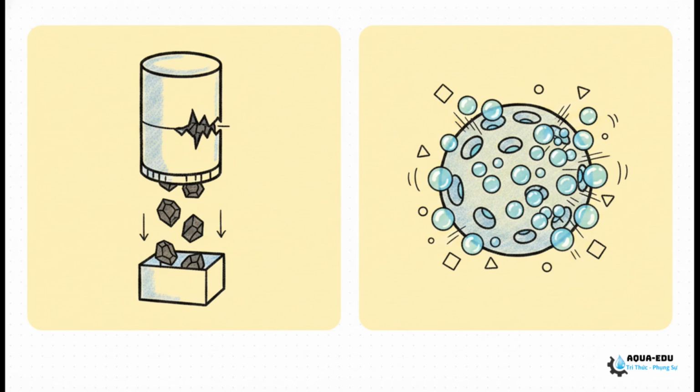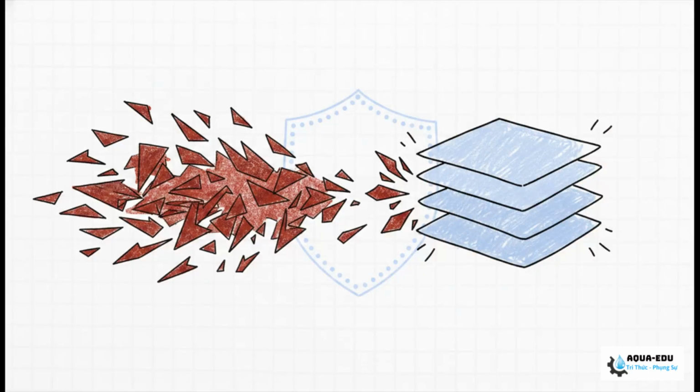CO2 is like a space hog. It competes heavily for ion exchange sites and completely overwhelms the resin's capacity to pull out other critical ions like silica. And your third prime suspect is actually a structural vulnerability in the plant's design.